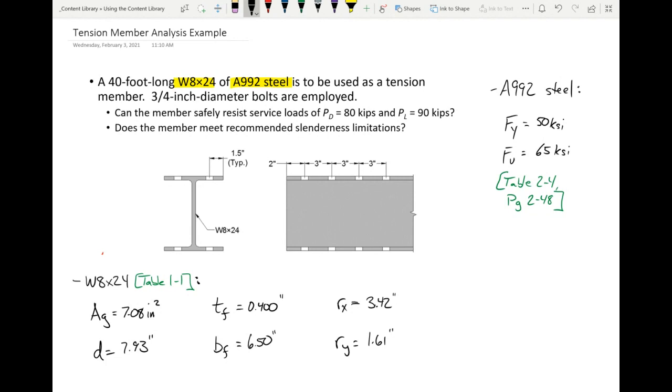In fact, it goes to the way that a W section is proportioned. We're talking about an I-beam or an I-shaped cross-section, and they are stronger. They have more flexural stiffness in one direction than they do in another. That's why they're shaped like an I shape. Basically what Zach said. So for every W section, RX is bigger.